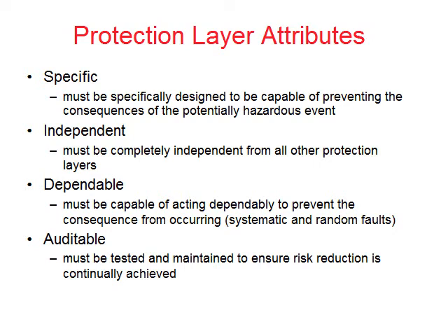Second, it must be independent. It must be completely independent from all other protection layers or initiating events. Third, it must be dependable. So it must be capable of acting dependably to prevent the consequence from occurring. So that addresses both the systematic and the random faults. And fourth, it must be auditable. So you have to be able to test it and maintain it to ensure you've got that safety integrity over the mission time of the system.